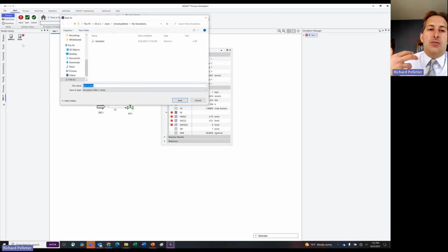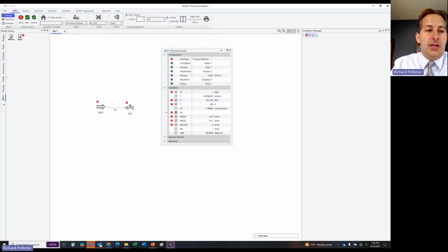So what that means is that now you've created that SimX file, you give it to someone else, especially for deliverables for this competition. They import the SimX file, and they're going to have everything they need to run your file. If you put your customizations in a different file, a different library, or even a custom library that you've created, that's only on your machine, right? So when you export to a SimX file, that information is not going to be retained, and your simulation is actually going to be pointing towards that specific model library for the custom model, right?